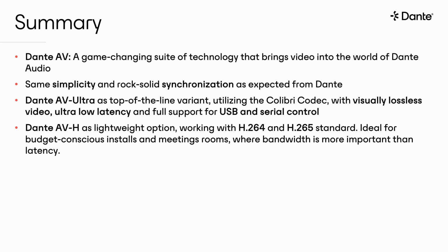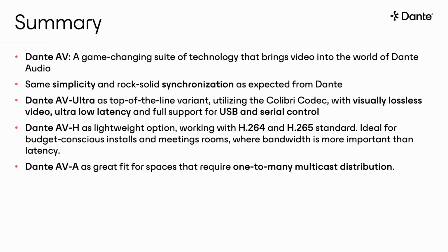Dante AVH is a more lightweight option that works with standard H.264 and H.265 codecs. It's ideal for budget-conscious installs like meeting rooms and classrooms, where latency is not a concern, but bandwidth is. Dante AVA is a great fit for spaces that require one-to-many multicast distribution.